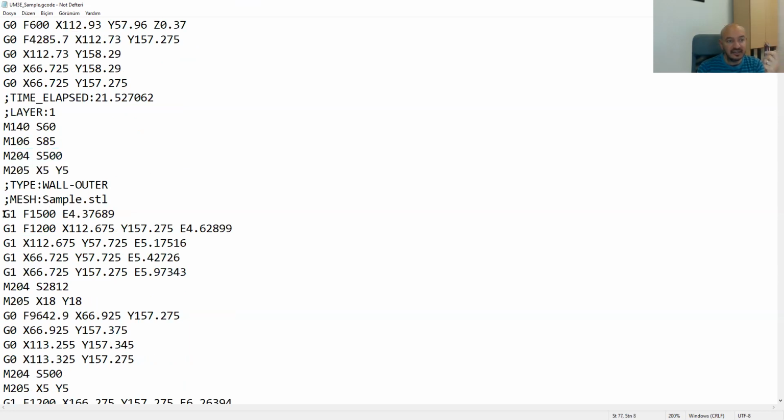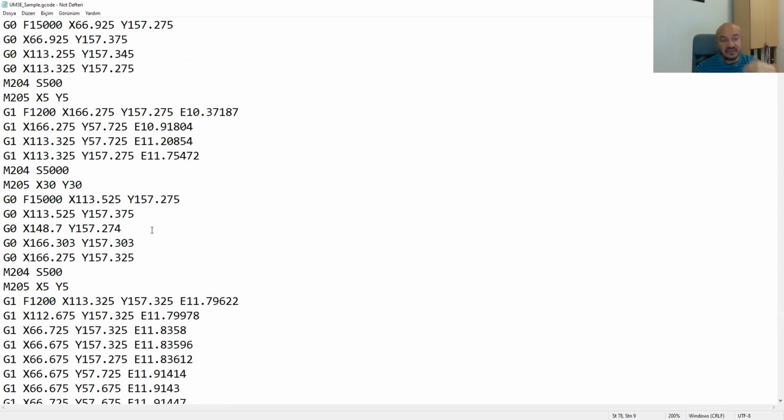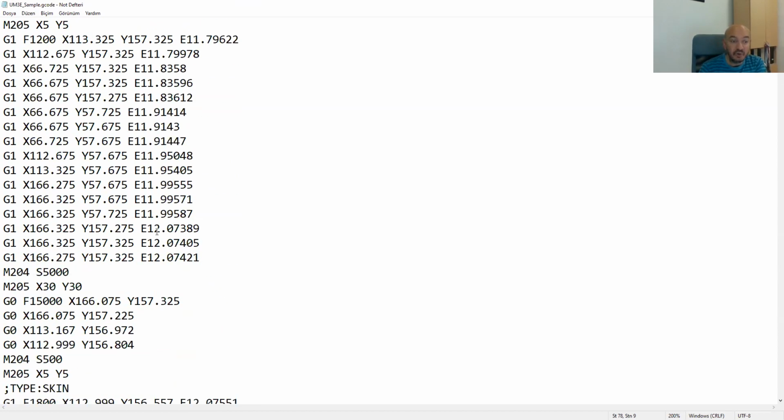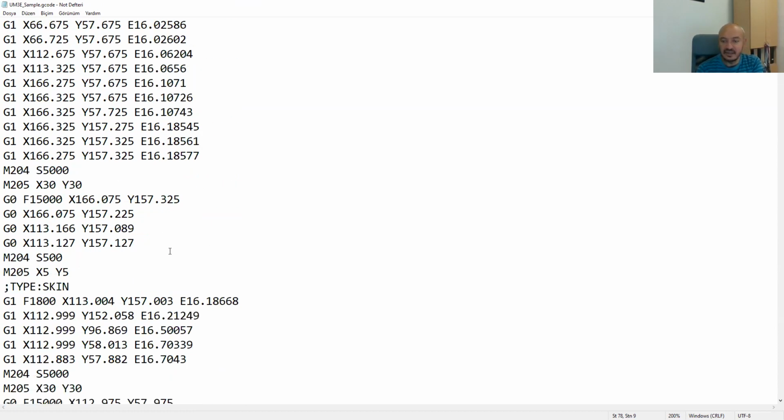And as you see, the feed rate is set, and the same amount of material is actually pushed once again. And later, we start depositing again with the help of these commands, and it goes like this. So this is actually repeating the same motions all the time until all the layers are fabricated. So how can we make use of this information?